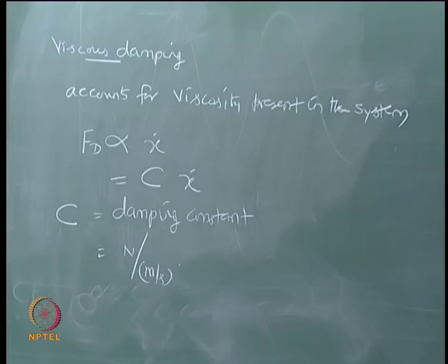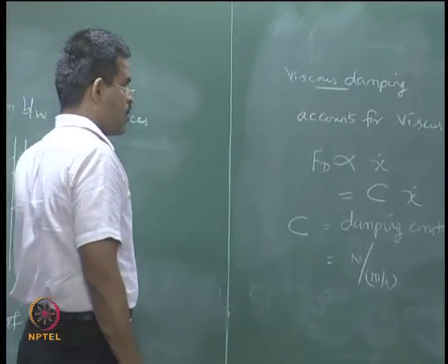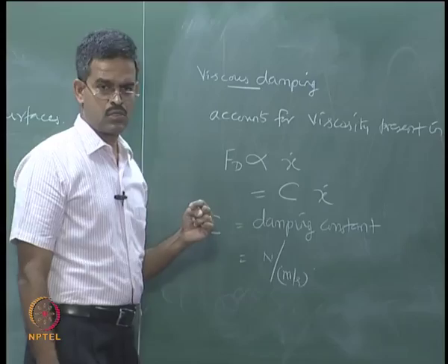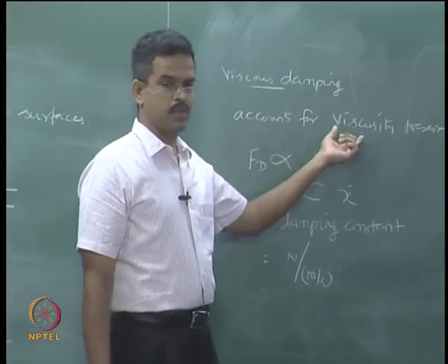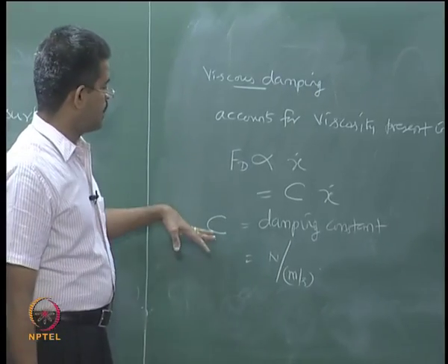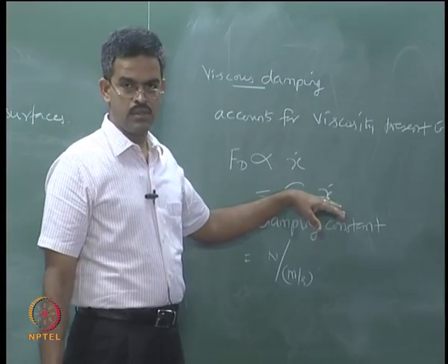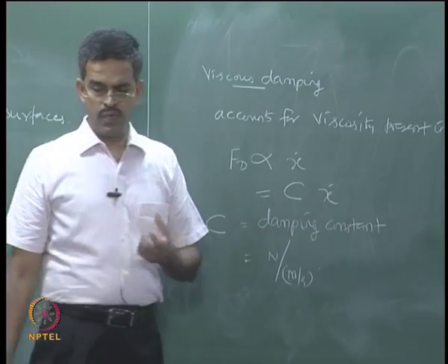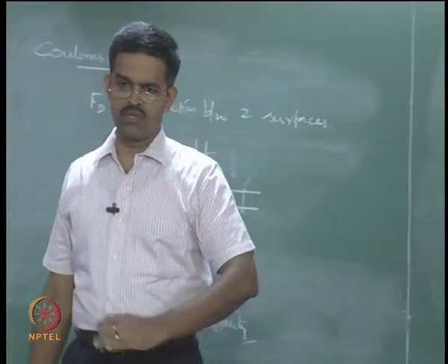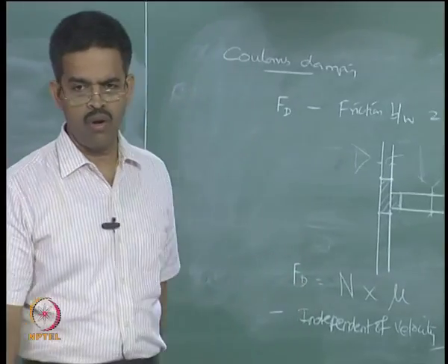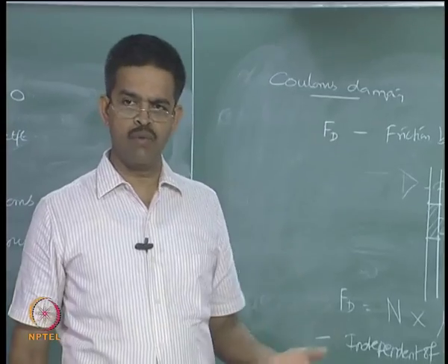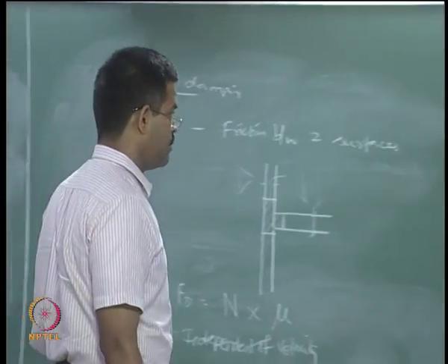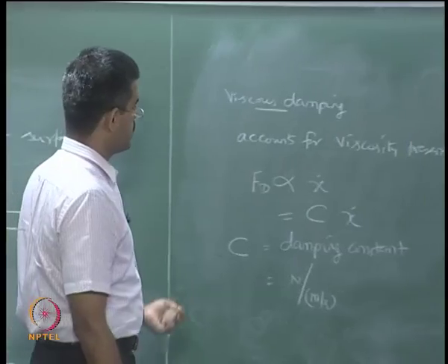And this is a very famous method of damping adopted in offshore structures or ocean structural systems, because we deal with fluid structure interaction and viscosity will be present in the system, and therefore our damping is proportional to velocity. Being a fixed base structure, still we will have velocity of the body or water particle. If it is a compliant structure, we will have relative velocity between the water particle and the structural member. So velocity will be predominantly present in both the cases.